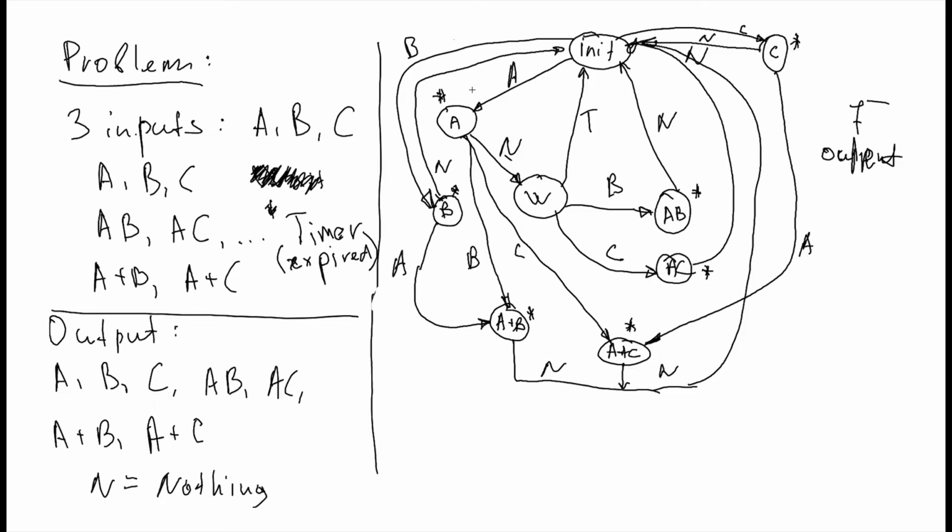You probably noticed that input encoder is a block that has 4 inputs and 5 outputs. Those 5 outputs go directly into the finite state machine. So if you combine the input encoder and the excitation function into the same design stage, then instead of 9 inputs, finite state machine would have 8 inputs. Okay?